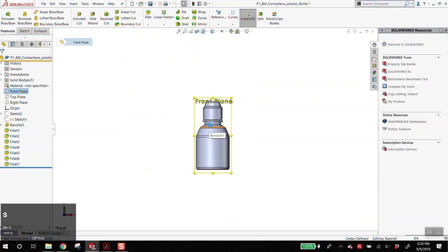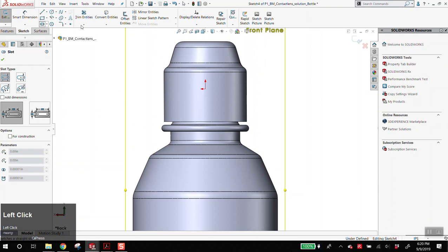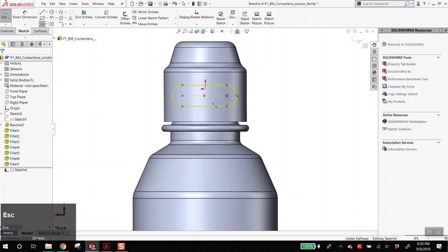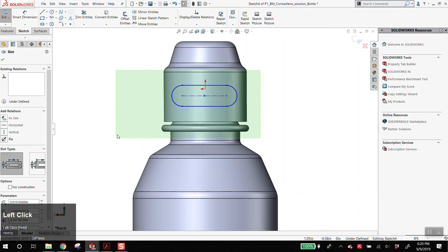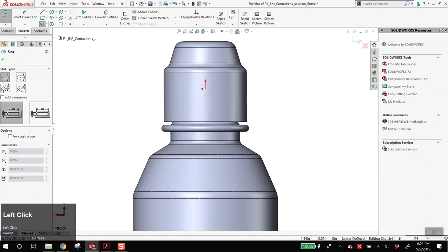So from a front view, and again, I'd like everyone to pay attention because this is essentially how you do it, as there was a question about how to emboss and deboss things. This is essentially how you do it for all of them. This is a good one to show you with because it's very simple. If we all remember Belinda's bottle, it had a bit of a detent in it that looked like this slot shape. Actually, I'm glossing over things. There is a slot drawing tool. The term we've been using in design show and tell is racetrack. The SOLIDWORKS term is slot.